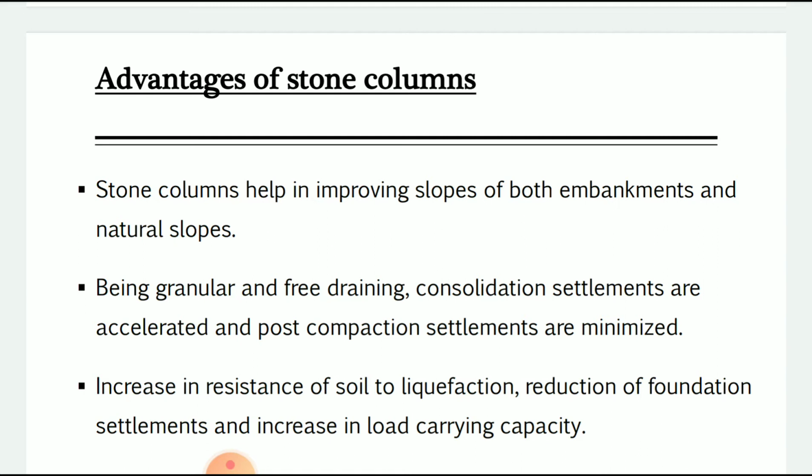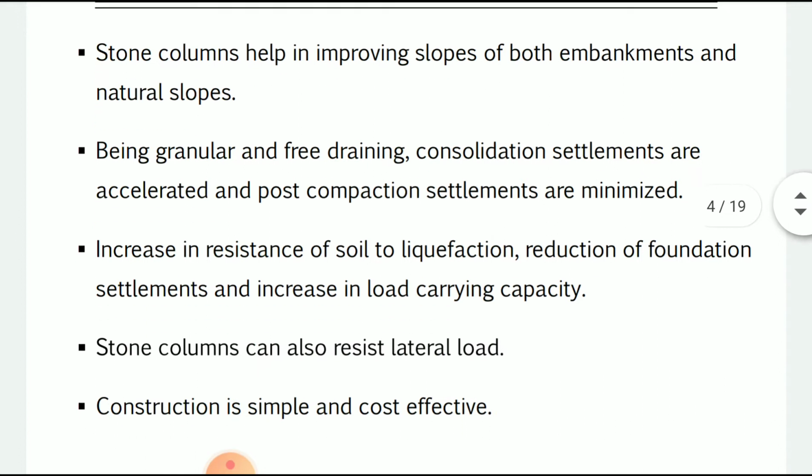Second, being granular, it provides very free drainage. Consolidation settlements are accelerated and post compaction settlements are minimized. There is an increase in the resistance of soil to liquefaction, reduction of foundation settlements, and an increase in the load carrying capacity. These are the advantages of the stone column.